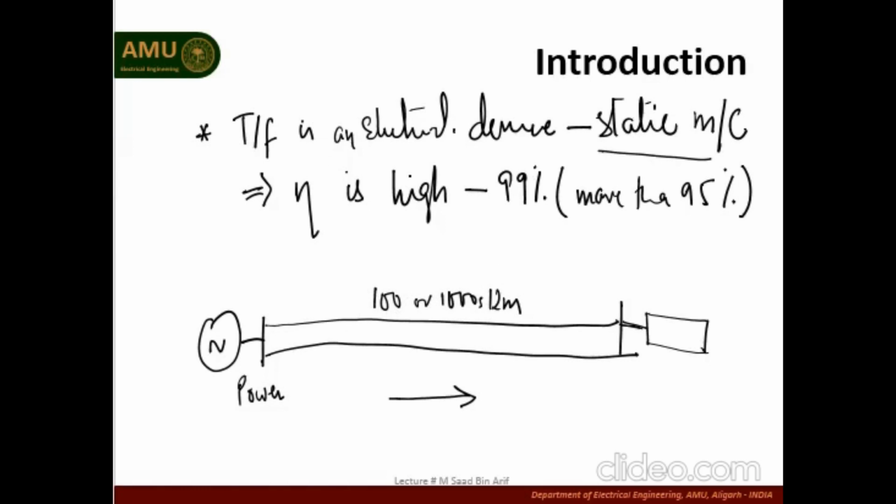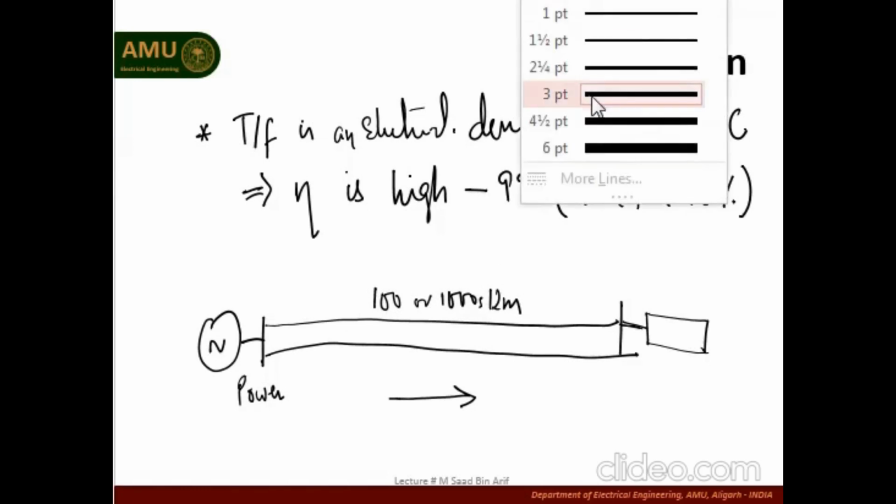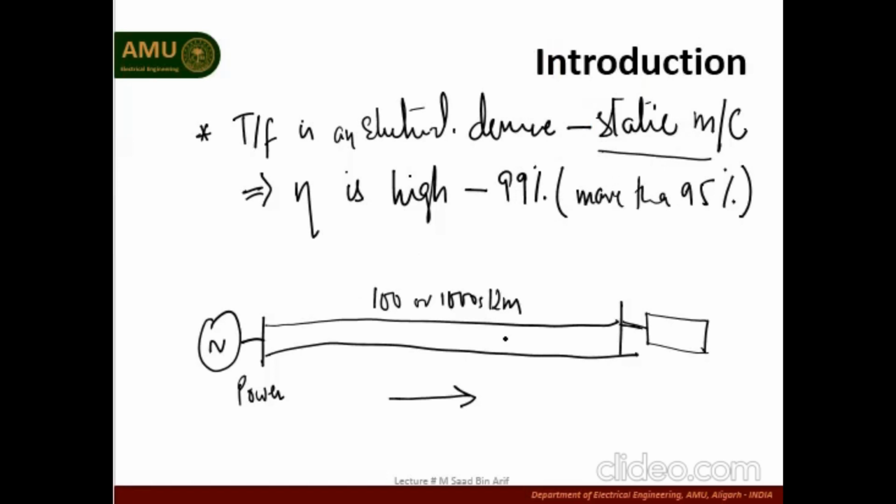So what is the issue with that? Why are we not able to transfer the power through this long transmission line? The issue is that this transmission line obviously has some resistance. Due to that resistance, if current starts flowing through it, the voltage starts dropping across this line. For example, if current I is flowing through it, then the drop is I into R1, where R1 is the resistance of this line. So the voltage here is V, the generating voltage, minus I into R1.